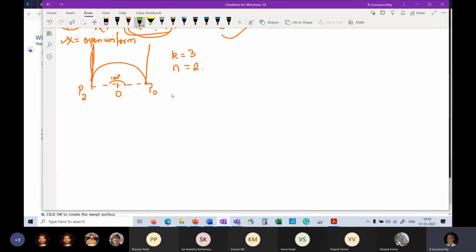So do we admit then that we cannot represent a curve which is beyond 179 point whatever? Or do we have a solution for this? Any thoughts? So by increasing the control points. By increasing the control points. Very good. That is indeed a solution.